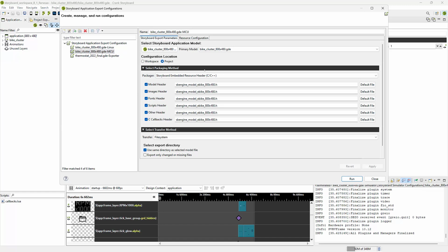The virtual file system is a special kind of header file format that we've created. And essentially, you'll see it shortly. Essentially, this is a way of laying out and encoding all of those assets such that they get compiled in and located in sectors in your flash. So it's a kind of linear addressing using XIP or direct addressing mode to the flash. We encode them, we deploy them as a header file, and that header file gets added to your project.